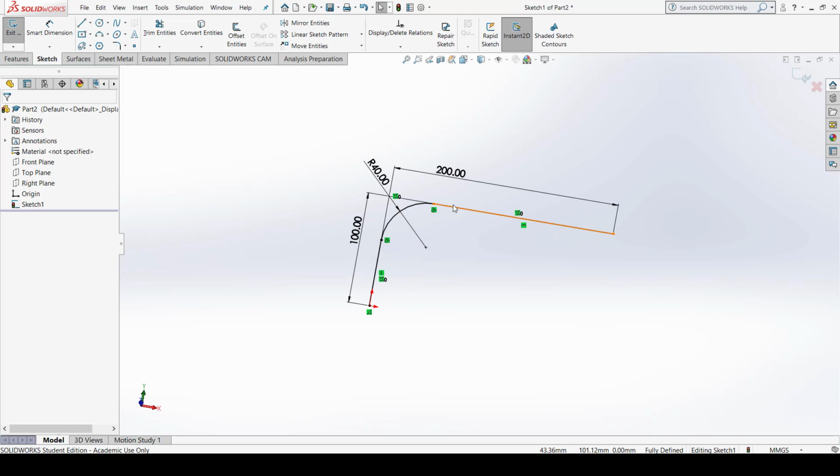So this is the core element of the command, through which your element propagates to form a pipe like structure. So for that I have to select this as a core or central curve on which your element, whether it is a circular element, a hexagon, a triangle, a square or a rectangle, any type of element, propagates along this central core and produces a solid object as per the shape of this central core. For that I have to select a plane.